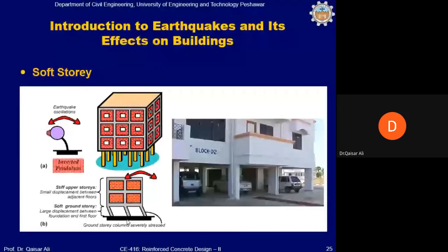When engineers analyze the structure, they must take these rigid walls into account. And when these rigid walls are taken into account in soft stories, the effect is included in the design, and there will be no problem. However, the building will be slightly uneconomical if there is a difference in the intermediate stories' stiffness, as happens in the case of soft stories.